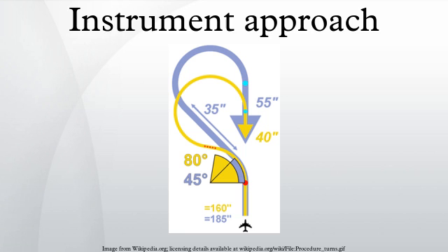Course reversal procedure. When conducting any type of approach, if the aircraft is not lined up for a straight-in approach, then a course reversal might be necessary. The idea of a course reversal is to allow sufficiently large changes in the course flown, without taking too much space horizontally and while remaining within the confines of protected airspace. This is accomplished in one of three ways: a procedure turn, a holding pattern, or a teardrop course reversal.